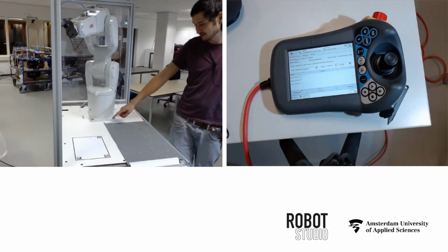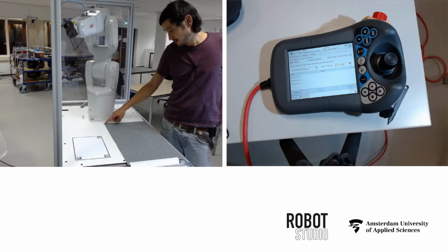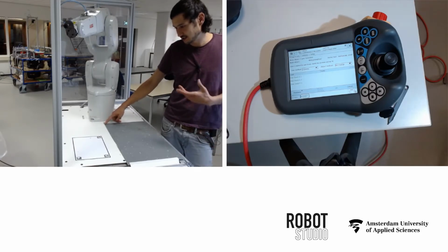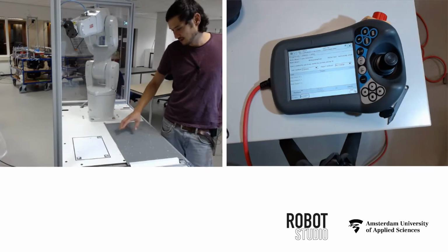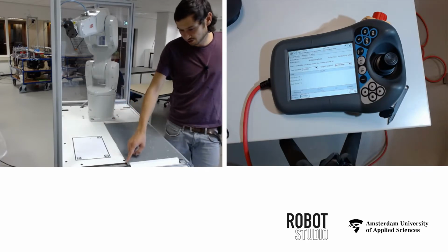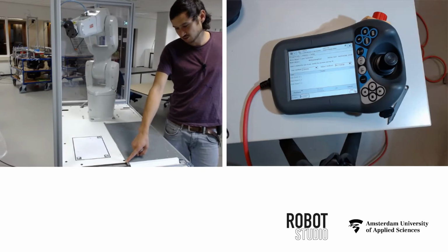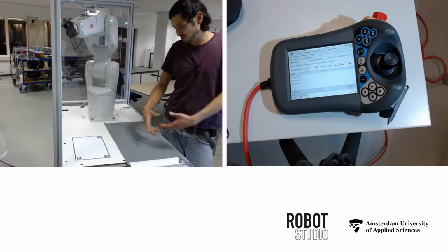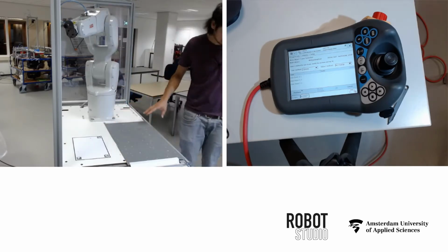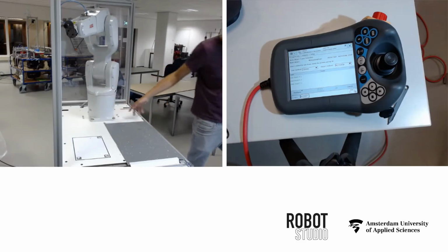It doesn't matter where it is on the line. However, if you choose it very close to your origin, then your jogging inaccuracy will be amplified. If you choose it further away, any jogging inaccuracies will influence your end result less. That is true for both axes, of course.